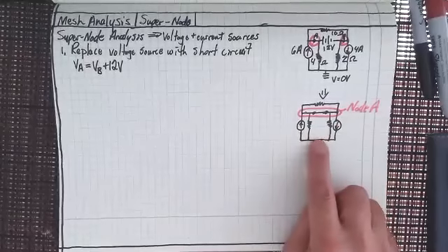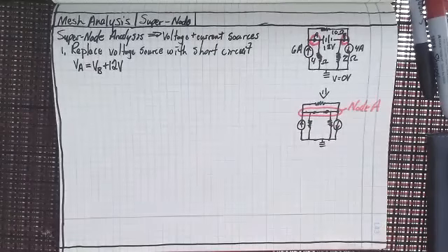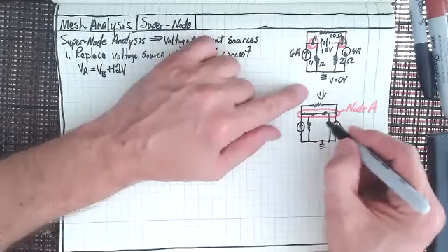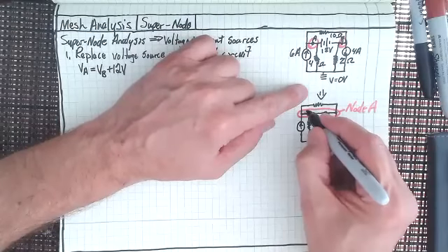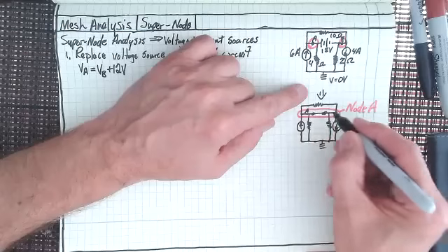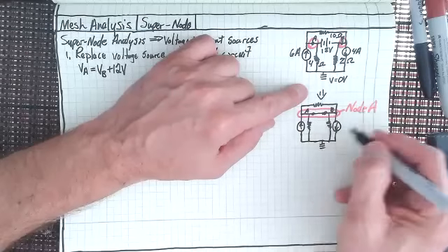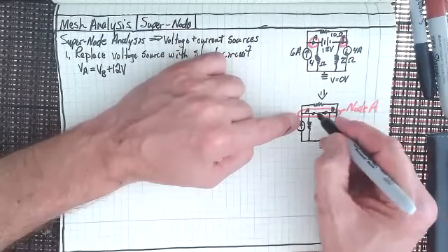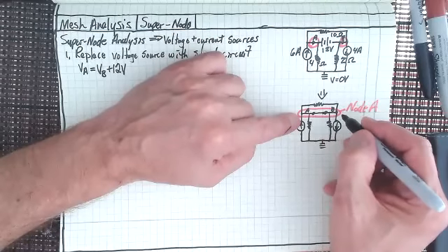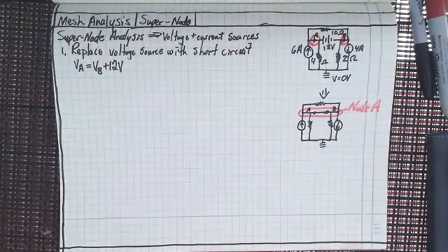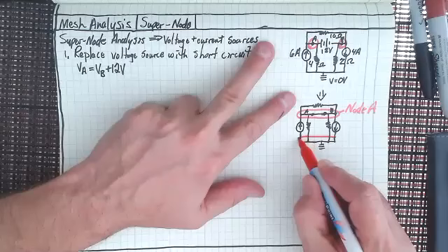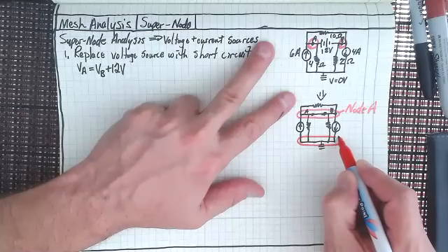Now, that's not for this circuit, though, because in this circuit, we see that the first thing that we're going to do is we're going to make node A contiguous, aren't we? So now, voltage at A and voltage at B underneath this supernode analysis is going to create one node with one voltage. Where would our other node be? Well, I think everybody can see that we've got another node down here, don't we?